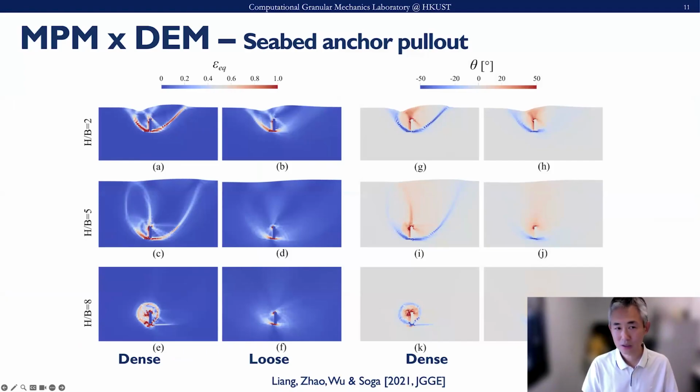placed anchor, when we pull to the right, it forms a shear band from the failure here. This whole pull-out also depends on the burial depth. This is the shallow burial depth, where H is the depth at which we buried the plate, measured to the center part, and B represents the width here.